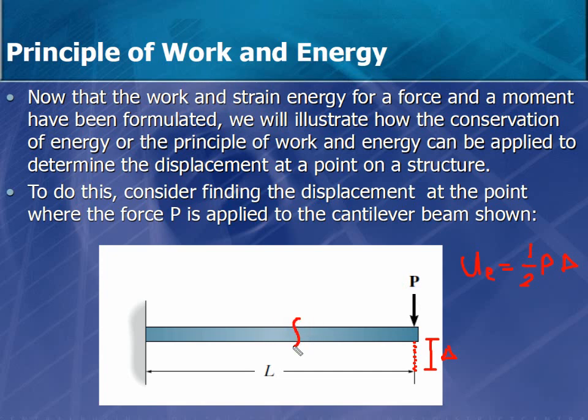What internal force do I have within here? Well, we assume that there will be shear, there will be normal force, and there will be moment. Now the normal force, since I don't have any horizontal load, will be 0. Shear, we said, is not going to affect the deflection here for us, so the only one remaining will be the moment.